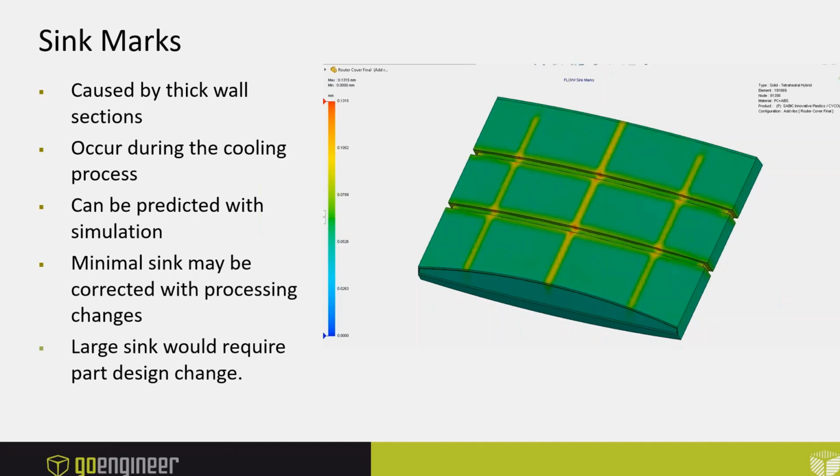Because this tells you how much texture you need to apply to your part so that no one can see your sink. If you look at the dashes of vehicles nowadays, this is a really good example of all the texture they put on there. Because that dashboard is so big, it's naturally going to have flaws everywhere. But if we know where those flaws are going to be, we can pull some out, and if we know by how much, then we can hide them.